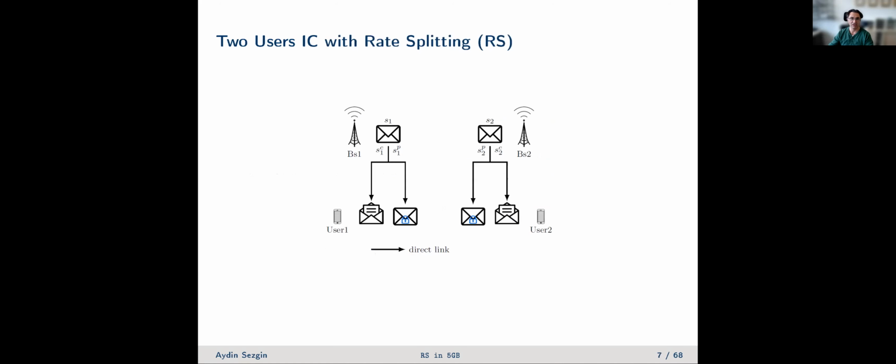Good. So how can we incorporate rate splitting? What is the idea? Let's look back at the figure we had before. What the users, or the base stations in this case, are doing is splitting their information into 2 parts. The first part is given with a superindex P, and the other part is given with the superindex C. P stands for private and C stands for common. And the idea is that the users are splitting this information into two parts, giving the receivers more degrees of freedom in how to deal with those signals.